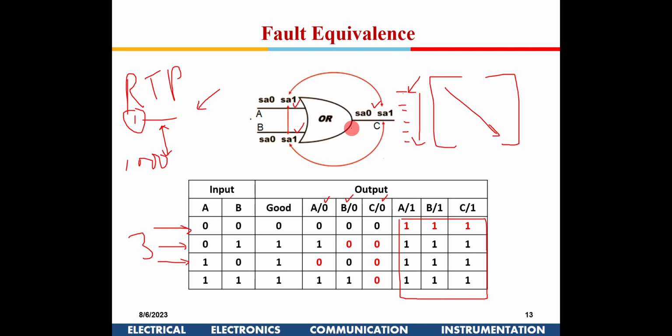One thing: if the input vectors A or B are getting stuck somewhere, will that be a problem of the gate, or of the input units? No, it could be anything. When we talk about a fault, the defect could be anything. The defect could be a short from the VDD line, or from the ground line, or it could come from the previous stage. We are not bothered very much about how that fault has occurred. We are not worried about the source of the defect.